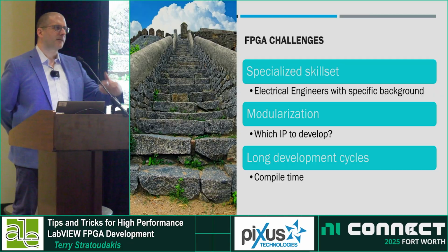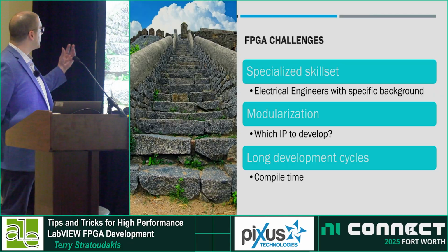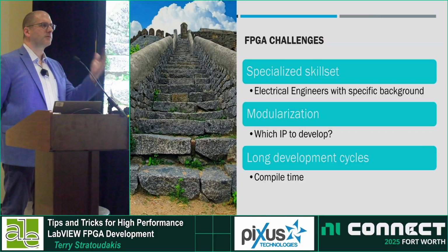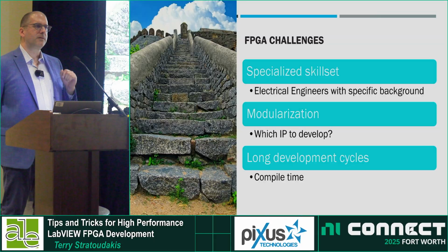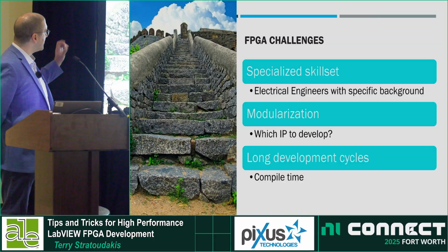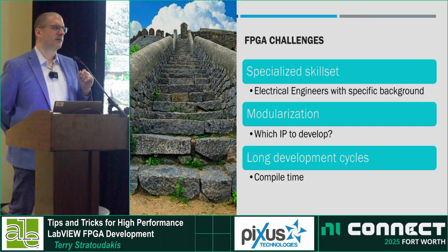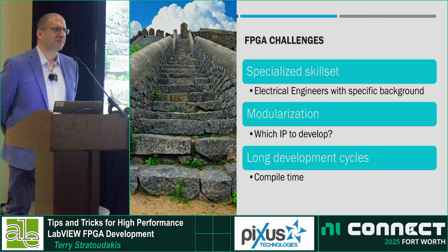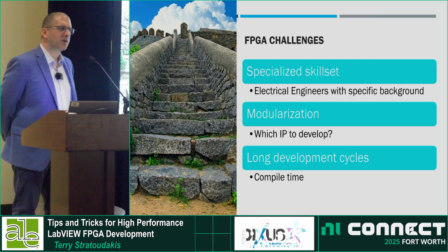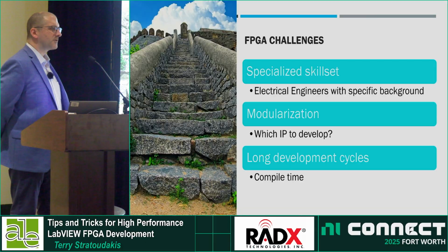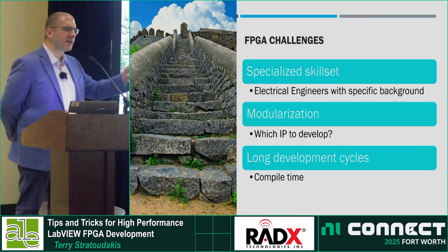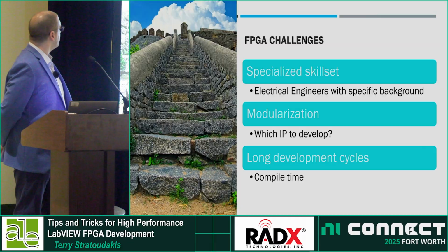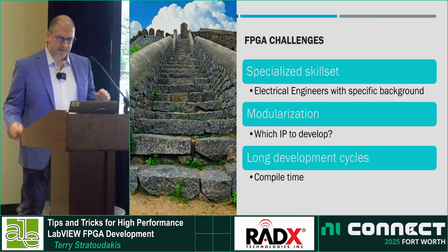When we develop logic to go onto an FPGA, we need to know what IP will go on there, and what will remain on our host side, or on our computer, or on the real-time side. So that's another really big challenge. What do we modularize? And then anyone that's worked with an FPGA for even one day will know that there are long compile times. We're talking about minutes, hours, overnight. So these are the challenges that we face.